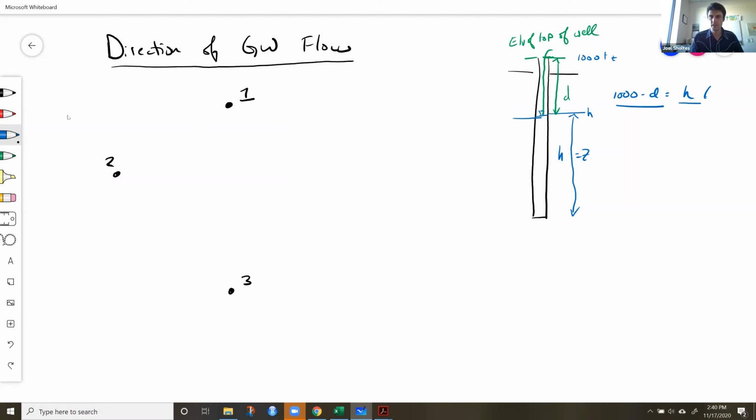So ultimately, we want to deal with the elevation of the water surface. All right, so we've drilled these wells in, and we've measured the head, meaning the elevation. In this case, H1 is equal to 26.26 meters. H3 is equal to 26.07 meters.